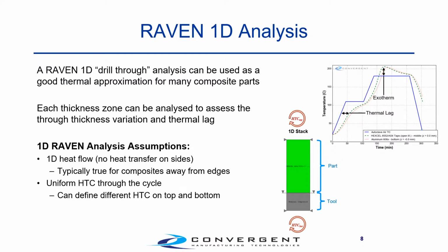Now this is a good way to represent many different thicknesses of parts or thicknesses across a part. And what it's going to allow us by applying these heat transfer coefficients to this stack up is to calculate the thermal lag as well as the exotherm where the heat is generated by the part itself.